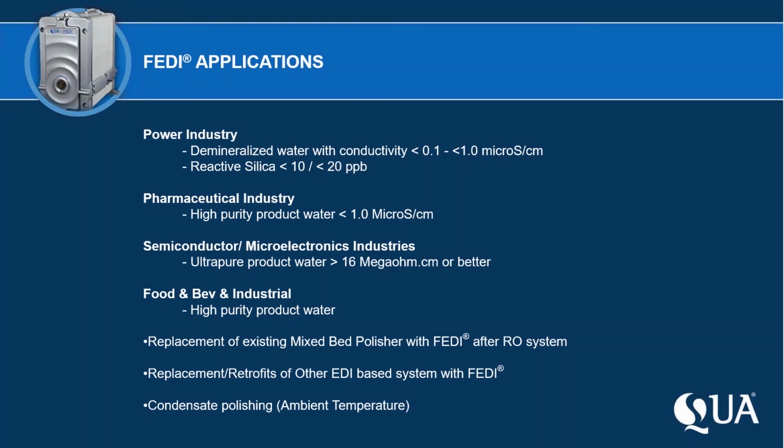Let's talk a little bit about pre-treatment, because we talk about post-RO systems. I'll have to say when EDI was first introduced, EDI actually competed with some of the reverse osmosis systems out there, where the pre-treatment was multimedia and scavengers, carbon tanks, and softeners.